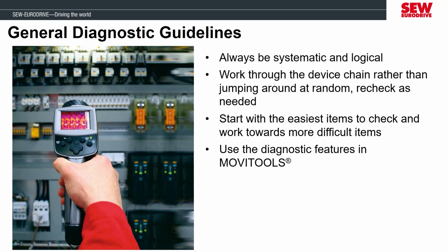If your motor is controlled by a MOVIDRIVE, one of the best diagnostic tools you have is the MOVITools software. If the problem situation is coming from a device that is in the same control chain of the MOVIDRIVE, then I would recommend to use the Scope tool to get a recording into the operating conditions of the inverter to narrow down if the cause is upstream of the MOVIDRIVE, such as the PLC, contactors, or supply voltages, downstream of the MOVIDRIVE, such as the motor, encoder, or load of the application, or internal to the MOVIDRIVE, such as the parameters, the IPOS program, or hardware.